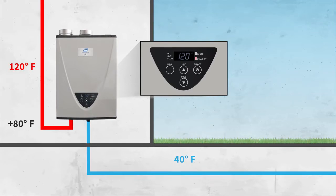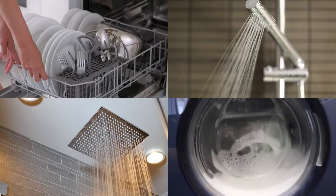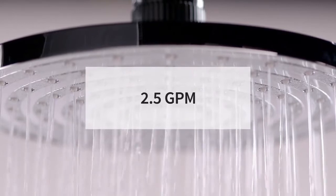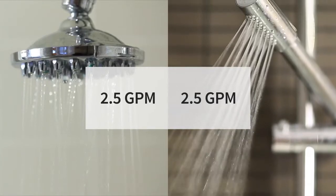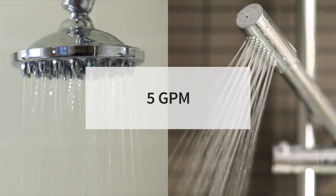Once you have established the temperature rise, you need to figure out the required flow rate to satisfy the peak hot water demand for the household. A simple way to calculate the hot water demand is to add up the flow rate of every shower or appliance that could be running at the same time. A typical shower head is 2.5 gallons per minute. So, if you had 2 showers that were running at the same time, you would have a maximum flow rate of 5 gallons per minute.